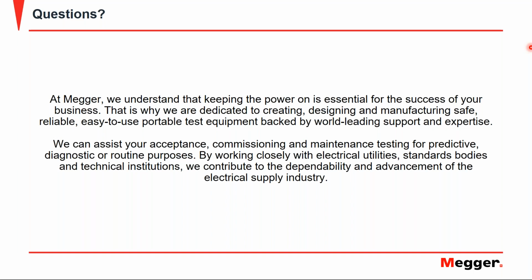So the other part of this question is if you have loose strands protruding from the terminations. What this is going to do is promote partial discharge, and it's going to give you negative test results whenever you're performing the testing, because it's going to promote partial discharge due to the sharp edges created by those loose strands protruding from the termination.